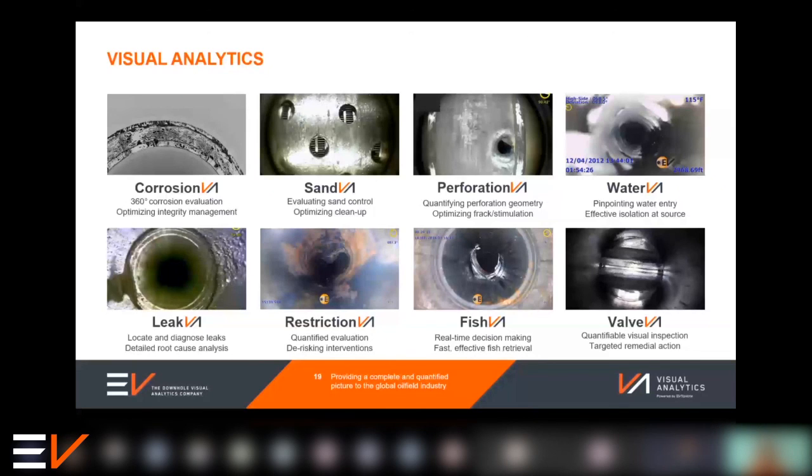Yeah, great question. It is something we thought about in the design. We knew that this is one of the likely circumstances and potential risks. So we actually have a ball-activated release mechanism. So if you latch onto the fish, but you can't pull free, you pump a ball. That engages a release mechanism, and you actually pull out of hole, bringing the camera with you, but leaving a fish neck behind that you might be able to go in with perhaps a more heavy-duty approach.